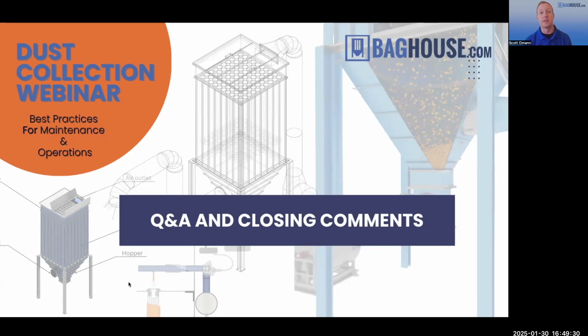The fourth consideration would be our collection efficiency. That means with our application, do we have to collect most of the dust, or do we need to collect absolutely the smallest of the particles and get nearly all of it out of the clean air? We want to consider those things, especially if it's hazardous or a toxic material, for example. Maybe we work in a field that's very highly regulated, so we want to make sure that we're collecting as much of the dust as possible, even those smallest particles as well.